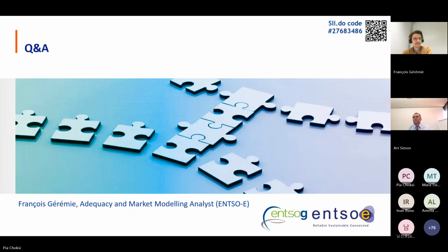Simon, do you have? Yes, I've seen this question. The different challenges between the summer and the winter analysis are that we can observe increasingly that in summer we need flexible capacity to ramp down due to excess generation of renewables. And in the winter it will be more and more about reliable generation or storage capacity in times of low renewable energy production. We have seen that storage capacity has increased proportionally very fast from last winter to this winter, but in absolute numbers it is still on a low scale. So this is, I think, maybe the main factor that we see in terms of differences between winter and summer.